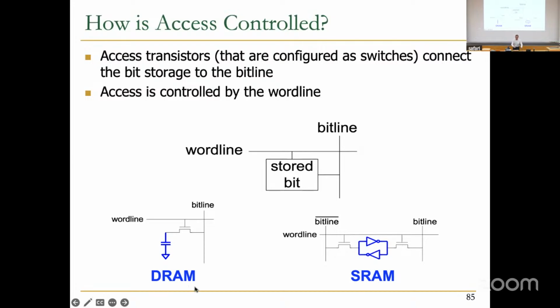Right? If this word line is not enabled, this bit line is not connected to the capacitor. As a result, the bit line stays at the level that it was, what's usually called pre-charged to in DRAM, a reference level basically. But if this word line gets enabled, the charge from this capacitor gets shared through this RC path, resistance-capacitance path, to the bit line.